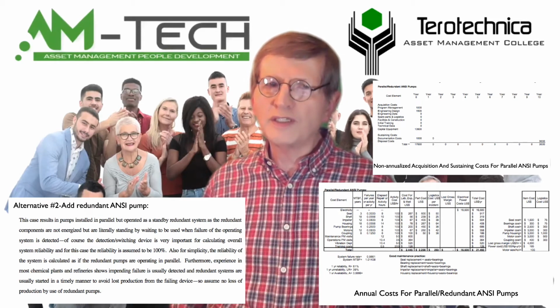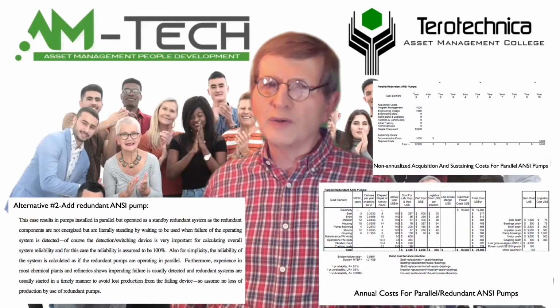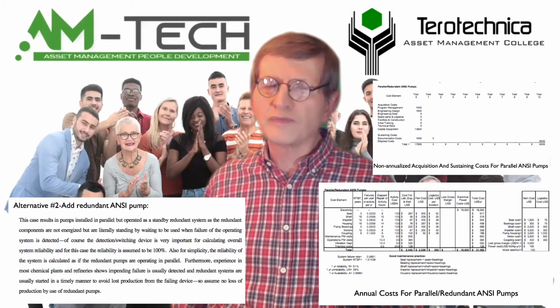Also, for simplicity, the reliability of the system is calculated as if the redundant pumps are operating in parallel. Furthermore, experience in most chemical plants and refineries shows impending failure is usually detected and redundant systems are usually started in a timely manner to avoid lost production from the failing device. So assume no loss of production by use of redundant pumps.